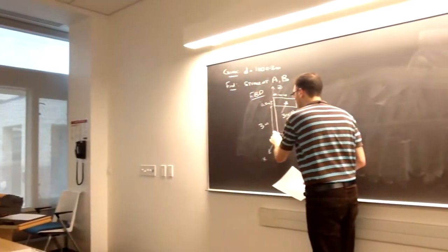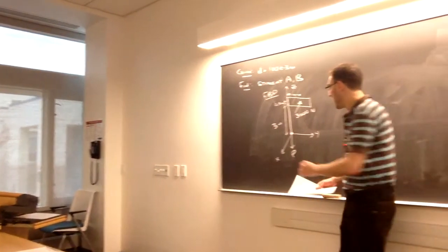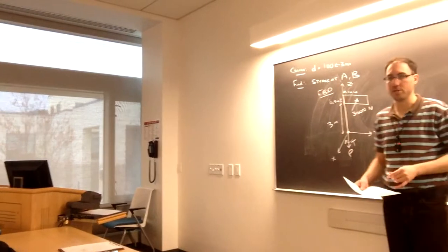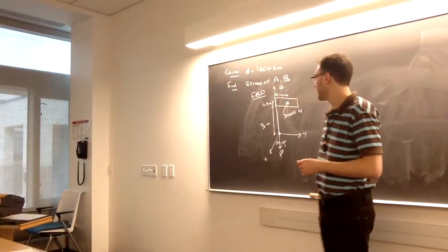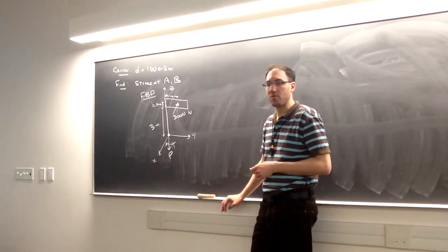So outward from the surface of the cut will be that normal force P, and positive around that arrow I just drew, that internal torsion T. I'm going to follow my coordinate system to draw.